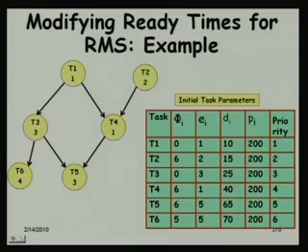Simple thing, just think about it. Since they are at the same level in the precedence graph, can they be given the same priority? No, that argument is not valid. See, what he is saying is whether tasks at the same precedence level can be given the same priority. No, that argument is not valid, because you also have to consider the deadline. What if T4 keeps on executing and T3 cannot complete before T4 completes? T3 might miss its deadline, isn't it? So, between T3 and T4, whoever has the nearest deadline, give it the higher priority.